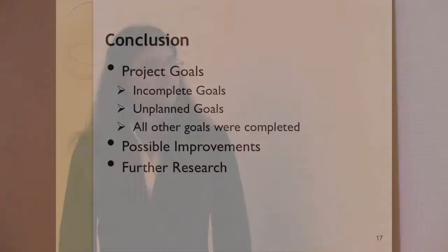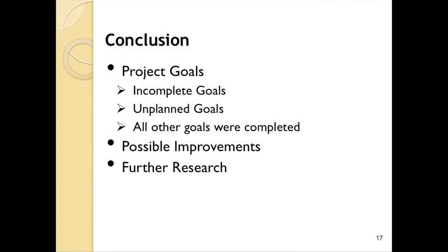In conclusion, we had 5 primary goals. The first was to actually create models for testing in the wind tunnel. The second was to test these models. We also wanted to gather our results and then analyze these results of the shock angles and standoff distances by comparing them to the theoretical values given by the NACA shock table and the standoff distance equation. Our final goal was to actually create a detached shock table for the cylindrical models that showed what the standoff distance should be based off the diameter of the model.